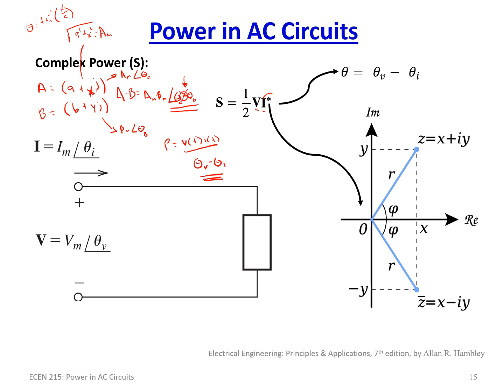However, if we take the conjugate, now we end up with this, which does provide us the ability to do this. We're just flipping the imaginary component. So that's all we're doing here mathematically. It's a mathematical, if you will, trick. It's not really much of a trick. We're just using a mathematical property to get us the actual power, because our goal is this, V of t times I of t. You just can't simply take V times I as a phasor to get there, because we'd end up adding the phase angles and not subtracting them. So that's what's going on here.